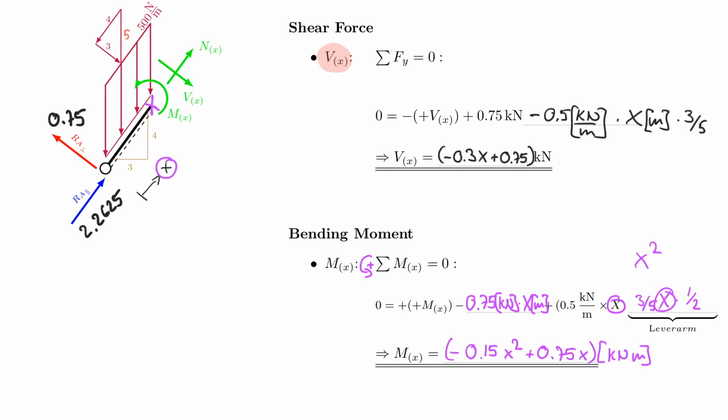And there you have it. So number one, if I plug in 0 into this equation, then my value has to be 0 because there's a hinge here. I mean, this is only a hint that I give my students, but ultimately there's just a support there. And so the support reactions have no lever arm yet. Therefore, if you plug 0 in, the moment must be 0 at this location. And that is true if I plug this in.